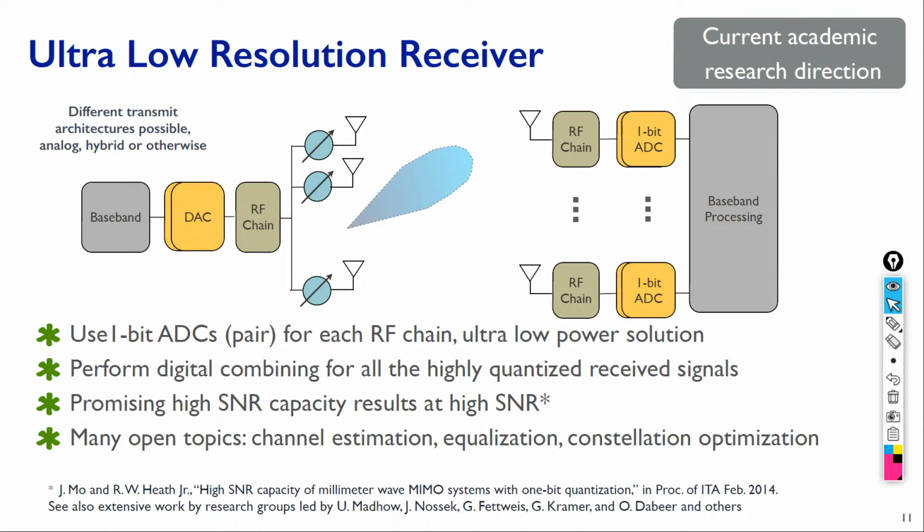In this case, since most of the complexity is coming from using RF chains and digital to analog, analog to digital, I can use, instead of analog to digital converters that are extremely complex and have many bits, a simpler alternative. The more bits the analog to digital converter has, the more levels you can use to quantize your signal, and therefore the quantization error will be less, which means that you can reconstruct your signal with less errors, with less quantization noise. And to do that, you need to have a high resolution analog to digital converter.